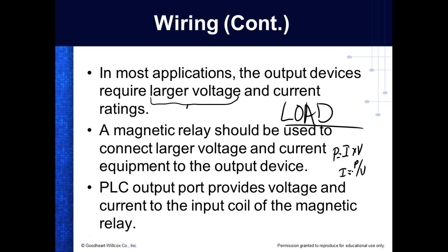So the only advantage of higher voltage is that you can use smaller gauge wire and smaller components. Your relays don't have to be as big. The little tiny small relays, right? You understand that? Because what determines the amount of power in a circuit? The load. And then the load is going to be rated around the voltage. All your high wattage loads at your house run off of what? 240.